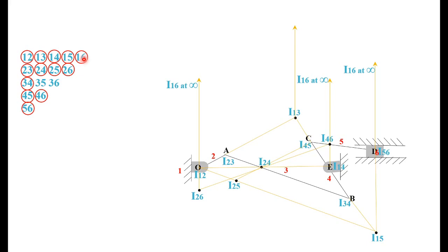So then you draw, you locate 1 3 to 1 6. So the line to infinity will be that line. Then next we have, in case of 3 6, we can choose the combination 3 4 6. If we choose 3 4 6, then the centers are 3 4, 3 6 and 4 6. So 3 4 and 4 6 are located. So you have 3 4 here, 4 6 here.